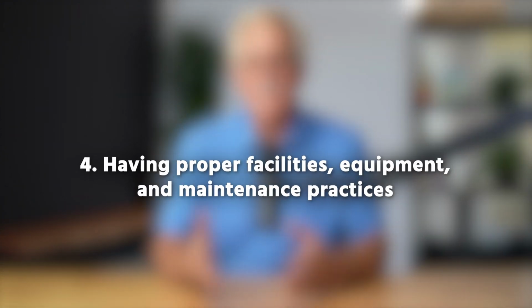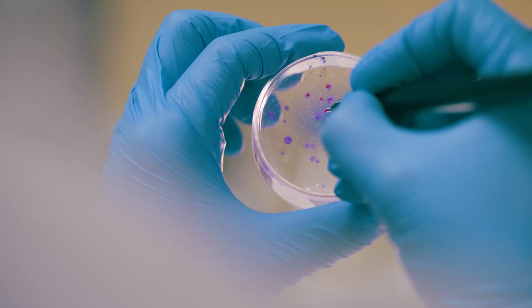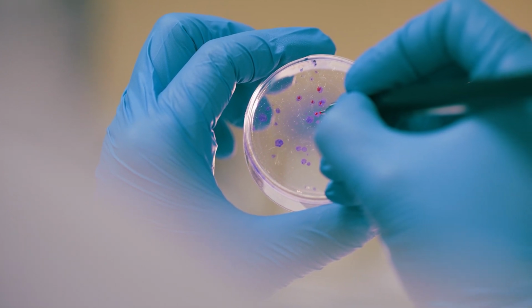Having proper facilities, equipment, and maintenance practices. The grounds and buildings need to prevent intrusion of pests and contaminant sources from water and air. Porous surfaces and cracks must be avoided to prevent places for microbes to grow. The risk of foreign objects getting into product from broken glass, metal shavings, hair, jewelry, or other sources needs to be prevented.